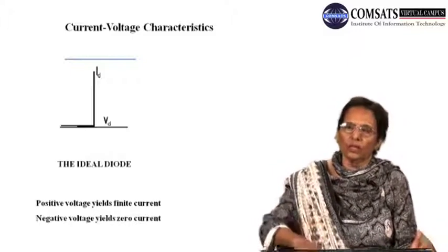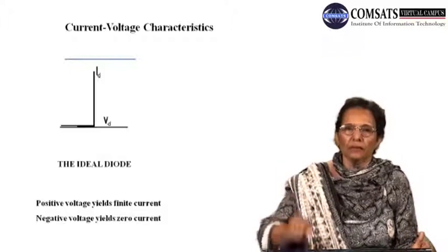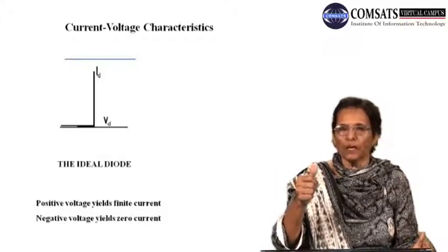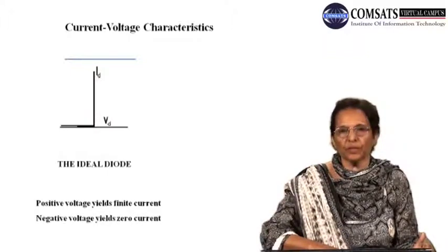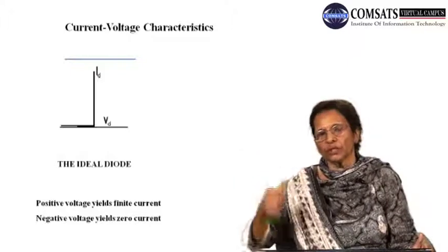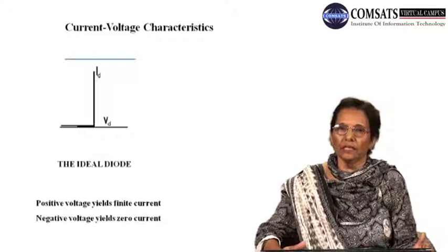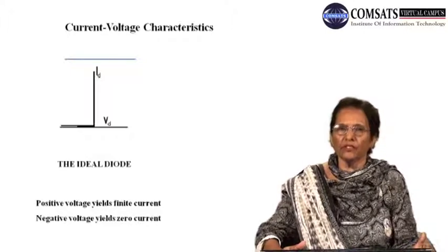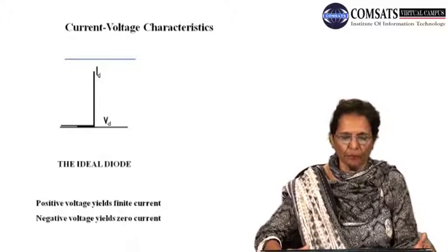You can control the amount of forward current, which rises exponentially, by choosing an appropriate applied bias and an appropriate temperature. This slide shows the so-called ideal PN junction. An ideal PN junction is the one whose assumptions we made in the last slide.